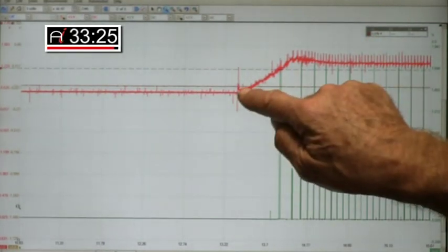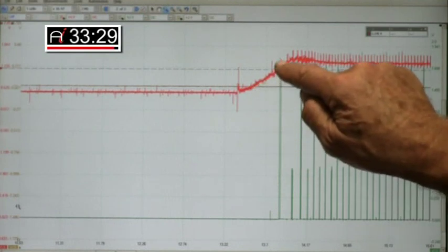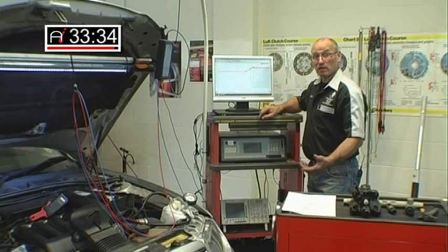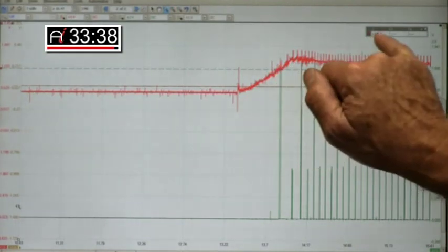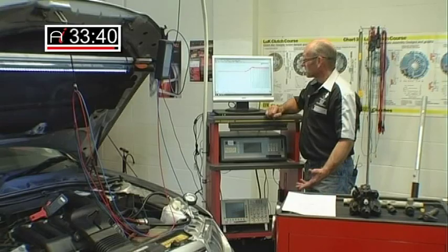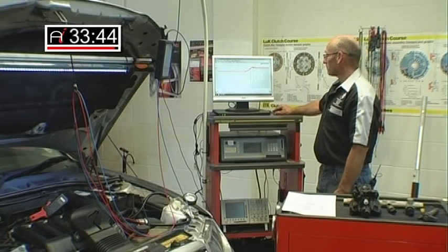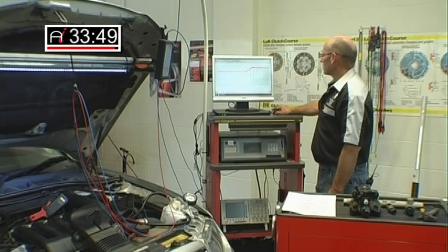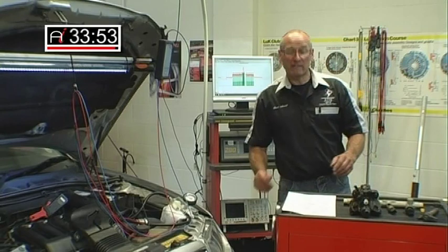And you can see that there's an absence of noise here, no injectors. And the first injector noise spike occurs there, which is caused by the opening and closing of the injector. The high current flow occurred at 1.176. So the system is behaving impeccably. If you don't make 1 volt, it ain't going to go. So, analysis complete. There's nothing whatsoever wrong with this vehicle.